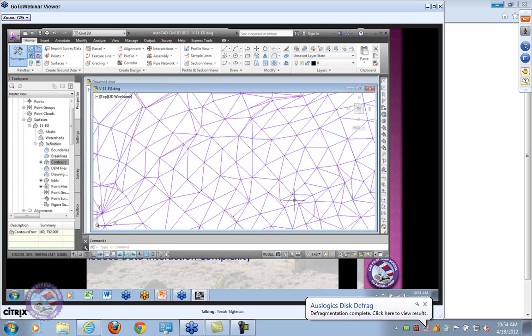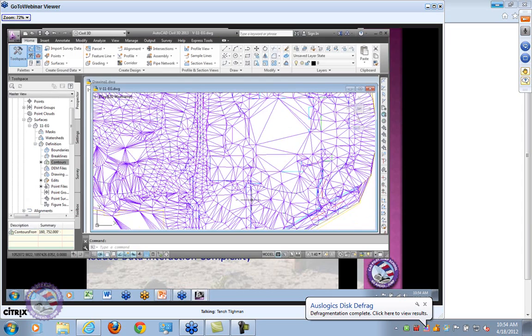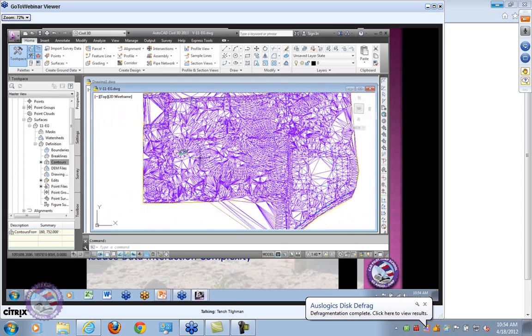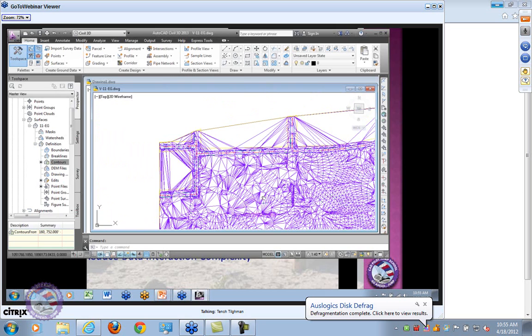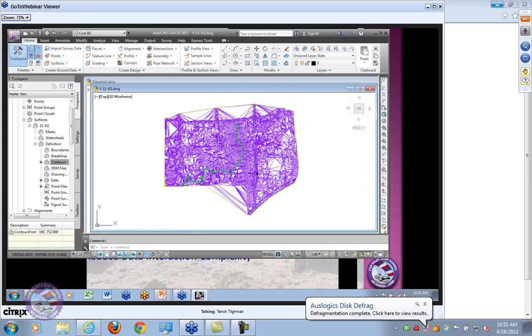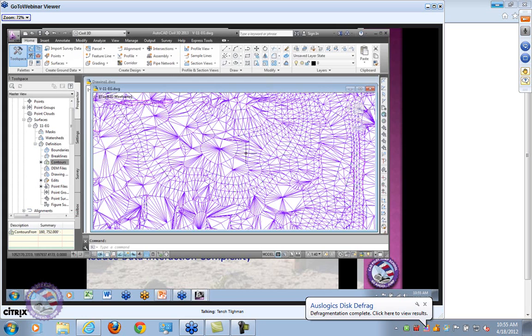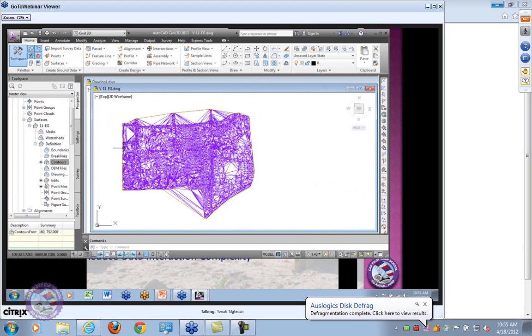You'll notice also that they almost get grid-like here because my weeding factor and my supplementing factor were very close to one another, and that's what my data spec was, 25 feet. That's what I told my guys to go out and shoot station, right? Okay, so they either shot 150-foot or 25-foot stations when they shot stuff. I told my photogrammetrist that's the level of detail I wanted for him to do field shots and supply me this data, and I ended up with that big pile of stuff.